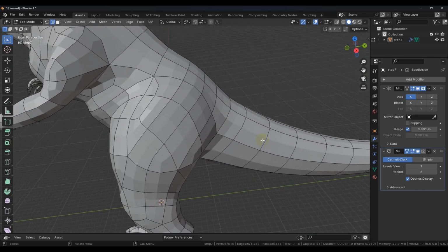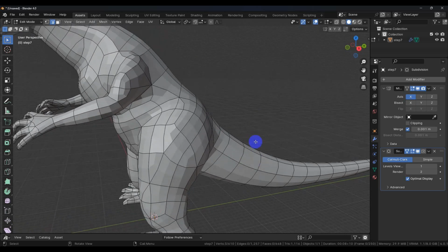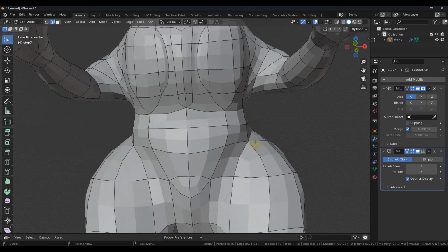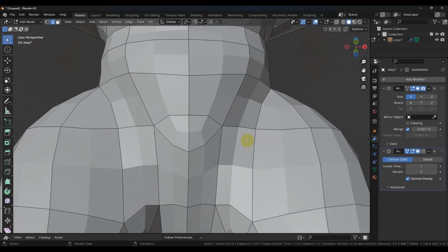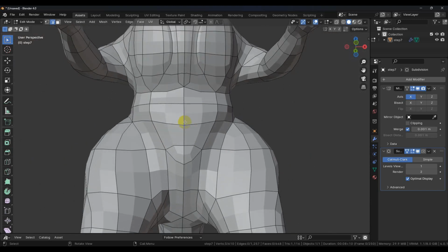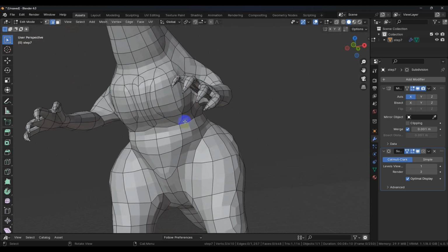You shouldn't be anal about it and worry about every single little triangle, because some of them really don't cause much trouble and some do. For instance, we have triangles here, but when we subdivide it, it comes around and the flow is really nice. So this is not creating a problem at all. But some of the other ones are creating a problem.